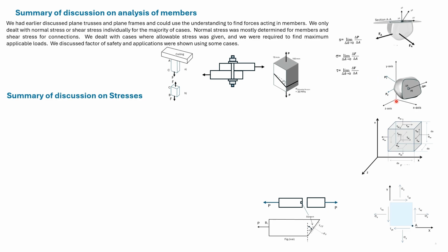We then take sections of the body parallel to the planes of the coordinate axis and passing through the point M. In this figure, we have taken a section parallel to the YZ plane. This arbitrary force is resolved into forces acting along the X, Y, and Z directions.